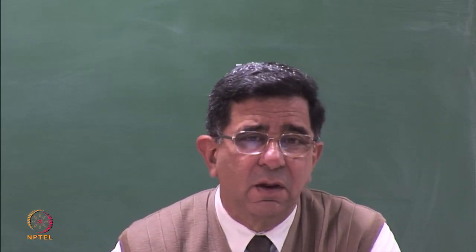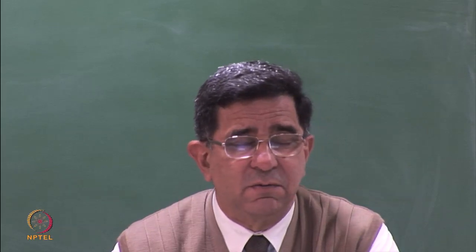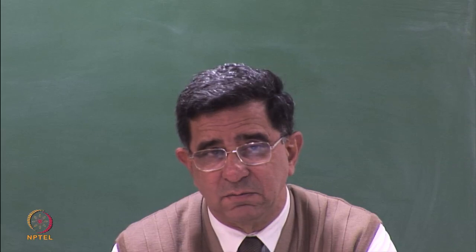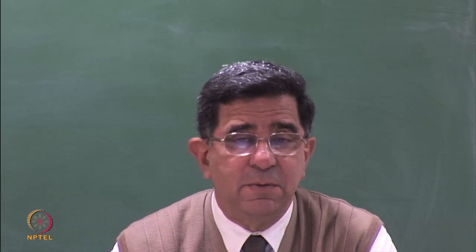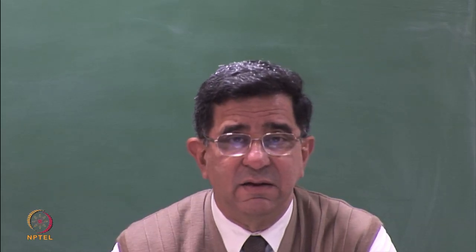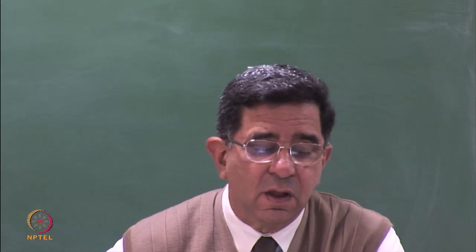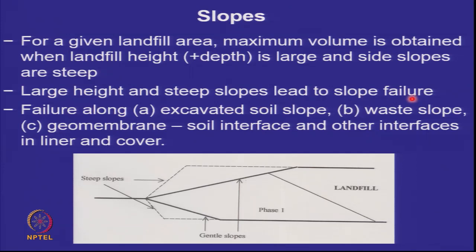The height can be larger. It's governed by aesthetics, and typically it stops at about 15 to 20 meters, but as I have said earlier, you can have larger heights, even as high as 40 meters. Landfills have been constructed in valleys and in side slope configurations. Large heights and steep slopes can lead to failure. If I give a flat slope at the top, and if I give a flat slope during the excavation, then the amount of waste that I can keep is much lower than if I can give a steep slope, both upwards and downwards. So always there is an attempt to make these steeper, and we'll see how steep we can go.